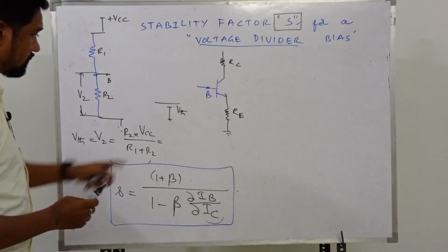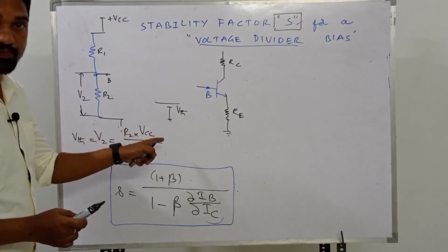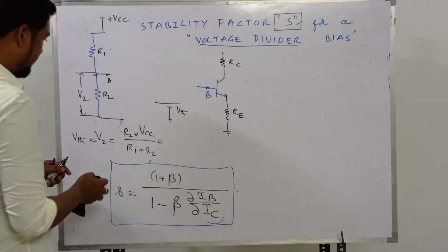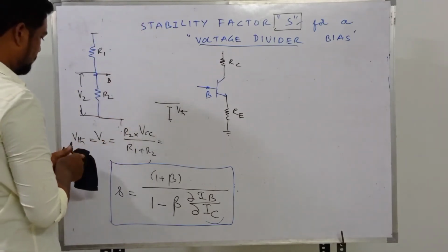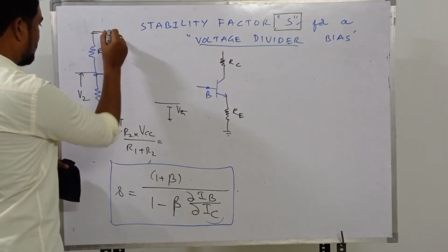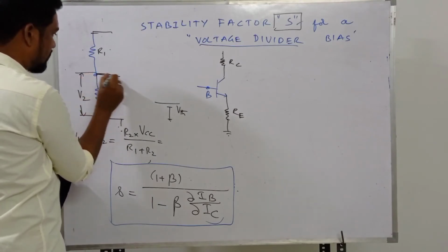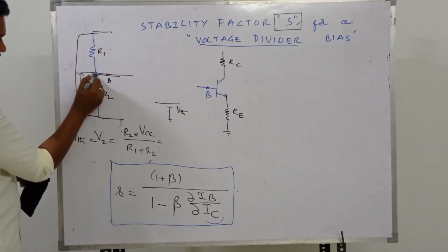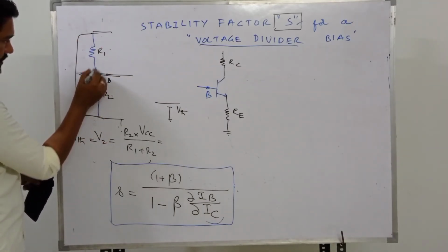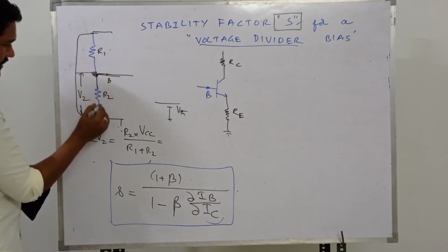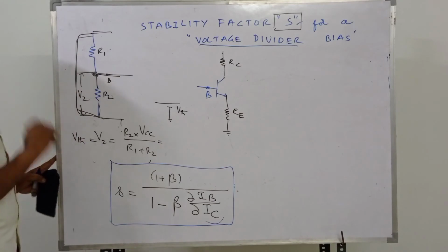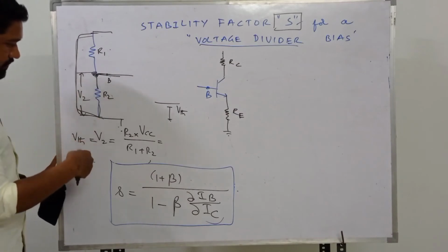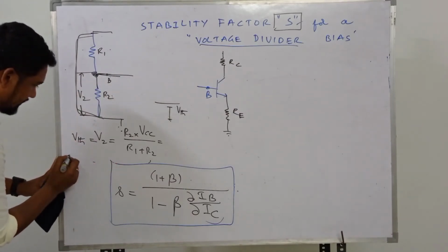And along with the Thevenin's voltage, we should have a Thevenin's resistance in series with the voltage, isn't it? So according to Thevenin's rule, how to obtain that one, guys? We don't need this anymore. Short circuit this one, short it with respect to base, okay? With respect to base, when we short it, it's like as if R1 and R2 are connected in this side, and R1 and R2 are connected in this side too. It's parallel. With respect to base, R1 and R2 are in parallel, removing the DC voltage. So RTH will be over this side.